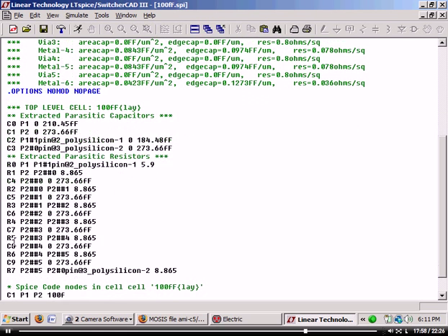Okay, it's extracting the capacitance. Yeah, but it shouldn't be this bad. Oh, it's only 8.85. All right. Yeah, so this is just extracting parasitics to ground, it looks like. So I can turn that off. Let's go ahead and do that and then resimulate.